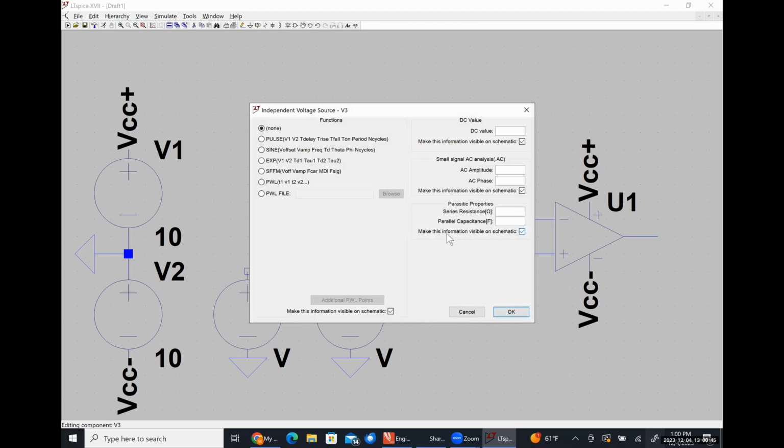There's a couple of different ways that we could do it. What I'm going to choose to do is to use a sinusoidal voltage and then just have it run for one cycle so that it will go from its minimum value to its maximum value. Okay. So I'm going to tell it to go for exactly one cycle. So a sinusoidal voltage usually goes from some negative magnitude to some positive magnitude, but I want it to go from 0 to 10.